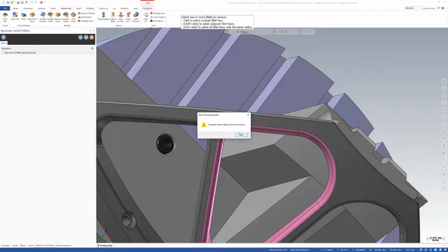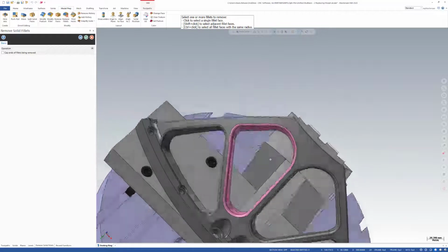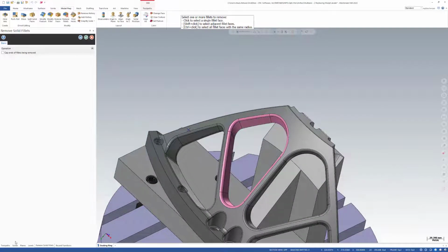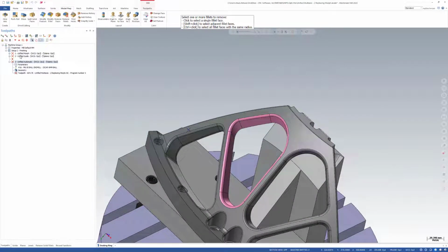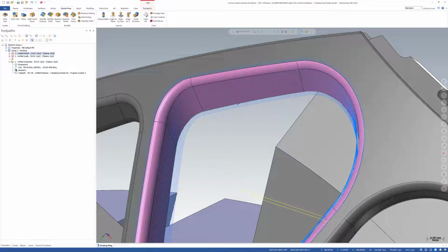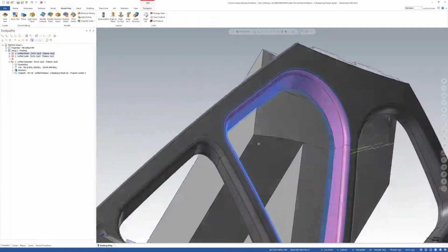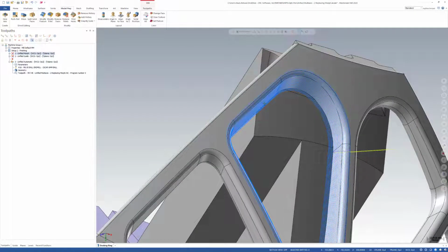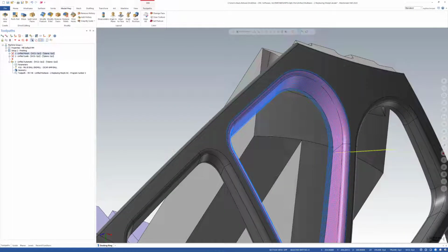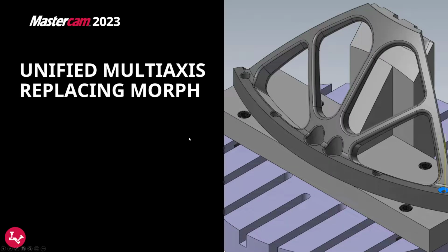We're going to have a couple angry toolpaths. We just deleted the input curves for the first two toolpaths. So I think if I try to regenerate everything, we probably aren't going to get anything good on the first two. It's going to yell at us for not having the curves. But Automatic still sees the boundary of this surface and generates a toolpath. So instead of having to manually reselect this new edge curve, Automatic is able to find it. So let's move on. That's a Morph.